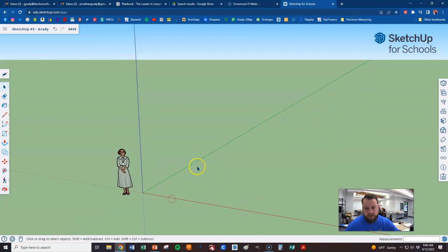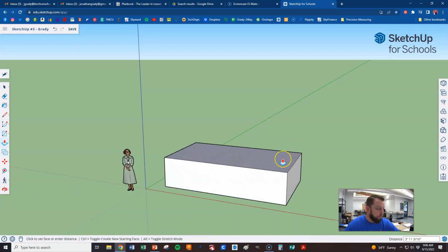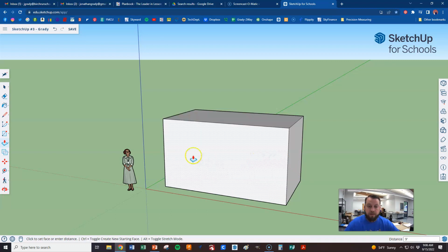All right, now we're going to do this fast. See if you guys can keep up here. We're going to hit R, click it, and we'll go 16 apostrophe, 9 apostrophe, enter. Good. We're going to push pull that up 9 feet. Good.